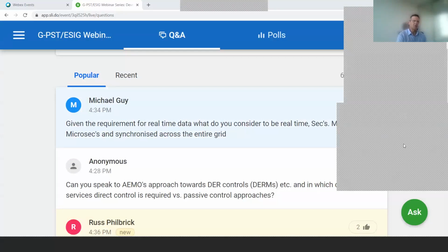But we're also looking to increase the number of installations of PMUs or phase measurement units in order to collect information that is more relevant and critical to system strength calculations and so forth, where phase angles are of primary importance. So the work currently going on is, first of all, the expansion on granularity by installing more SCADA-based high-speed monitoring equipment, as well as the increasing installations of PMUs to include then further measurement data. With the granularity that is for SCADA 4 seconds, for the high-speed stuff in the millisecond time frame.